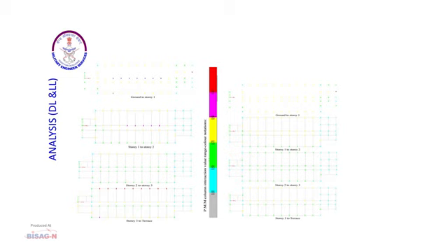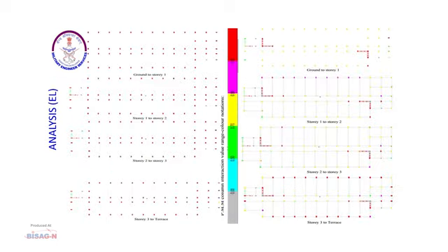To restore them, we have increased the grade of these columns from M15 to M30 by application of carbon fiber and micro concreting, and we did micro concreting to all the cracked columns. However, in seismic analysis all columns were failing, so we provisioned shear walls to arrest the lateral forces.